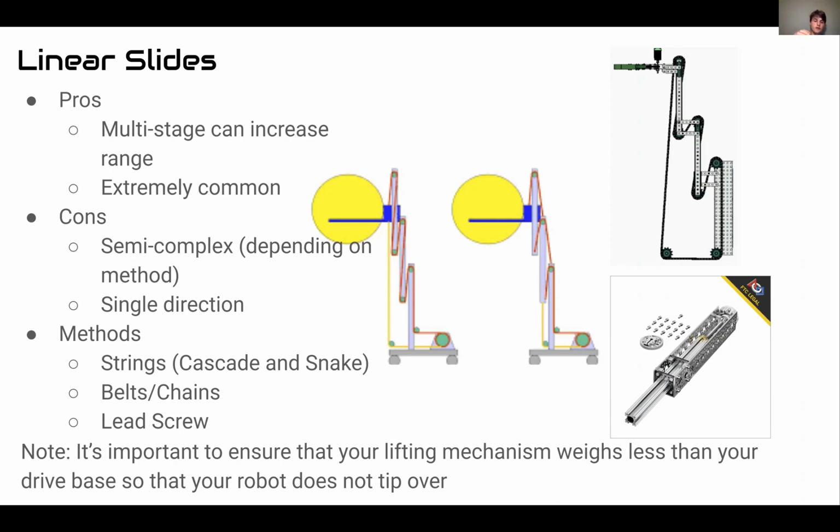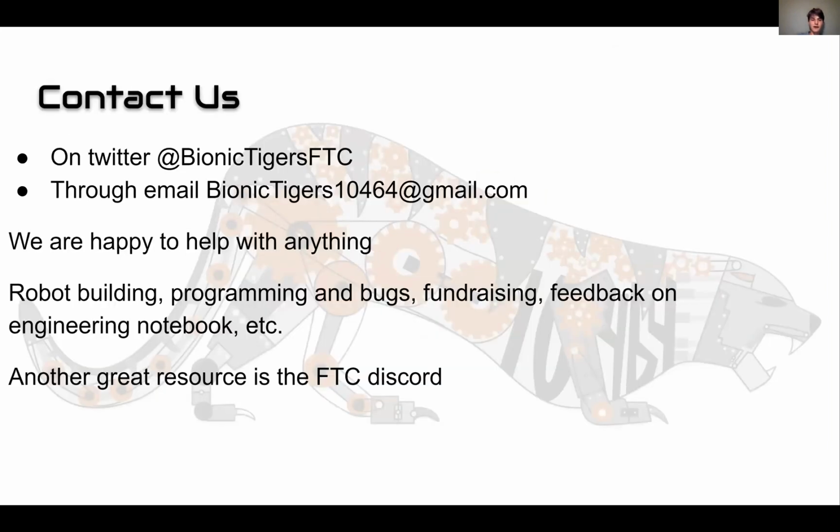So you just have to make sure that you have a heavy enough drive base that when you lift all of this stuff up in the air and you start to go forward, your inertia doesn't carry you over and tip you over, which is a mistake that we've made very often.